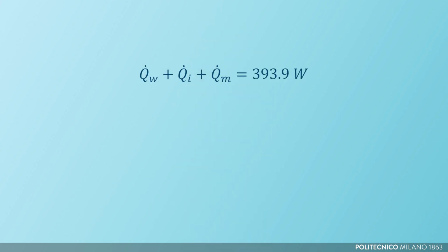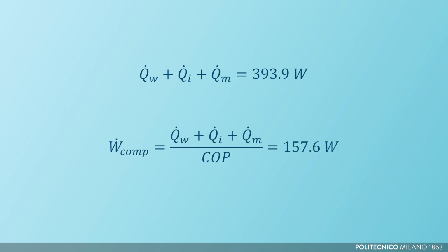resulting equal to 279.7 watts. This power is consumed during the initial cooling of the meat from 39 °C to 4 °C. Then the refrigeration load for keeping it at this temperature reduces, and it can be calculated as the sum of the heat gain from the ambient through the room surfaces, the heat gain from air infiltration, and the heat gain from equipment and lighting, corresponding to 393.9 watts, requiring 157.6 watts consumed by the compressor.